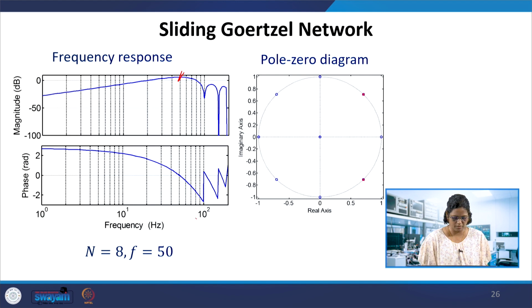1, 10, and here is 50, this is 10 power 2. The scale is adjusted to have this 50 hertz shown in the frequency response. So the pole is cancelling the zero at this point, getting the output only the fundamental here, and DC will be eliminated, the second harmonic will be eliminated, similarly all zeros where they are placed will be eliminated from the input signal.